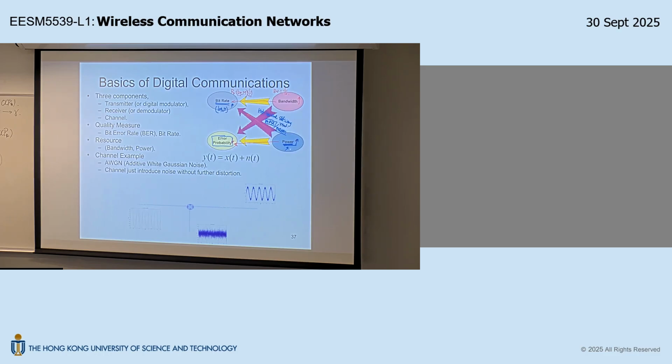So in a cellular network, which is what we call a wireless access system, usually you cannot have this kind of thing. This applies to cellular networks. This also applies to Wi-Fi. If you look at the design of Wi-Fi, again, you never come across 4096 QAM. Okay? There is one exception, which I used to work with Huawei on. I helped them to design a 4096 QAM system for a cellular network. But this 4096 QAM system is not for access. It's not for base station to user. It's for a backhaul, that is between base stations. Sometimes they want to set up a wireless link, and this is a wireless backhaul.